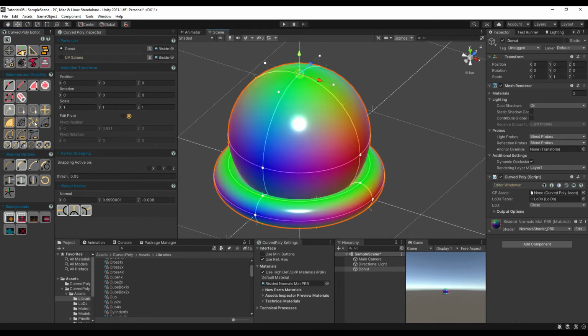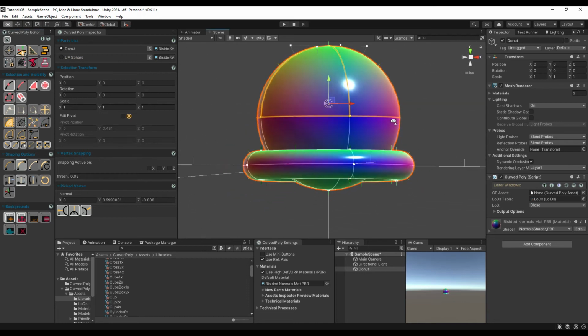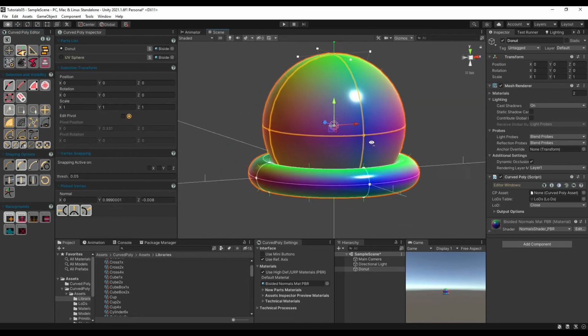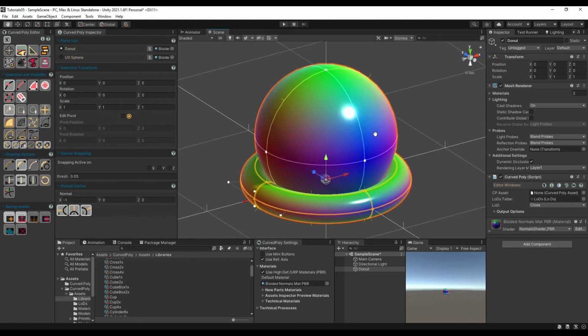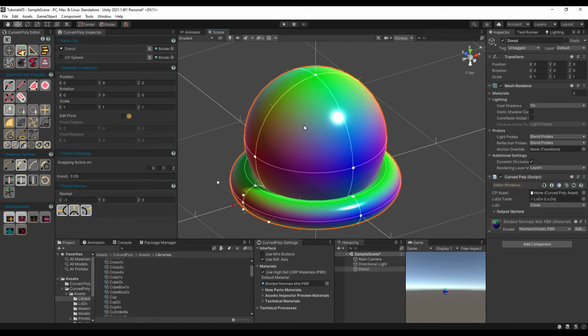For example, if we select a vertex and press Grow, every edge or polygon attached to that vertex will be selected, and we can click Grow more times to propagate the selection to more and more elements. Together with the buttons for instance selection, we can find the controls required to hide or show elements. Indeed, elements can be hidden in order to temporarily remove them from the editor. The hidden elements can be shown back to be visible again.